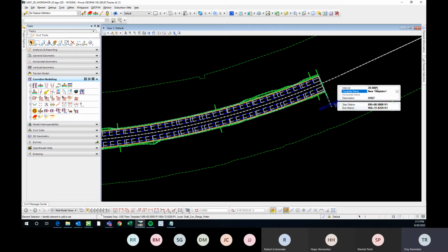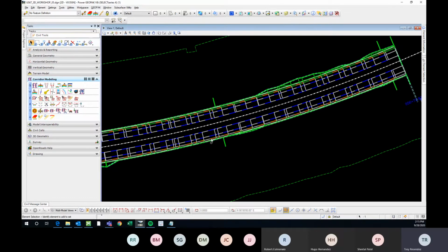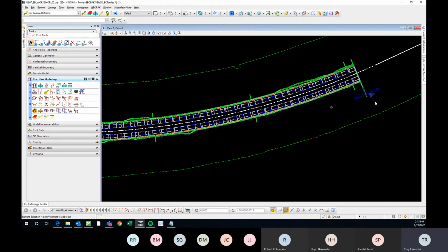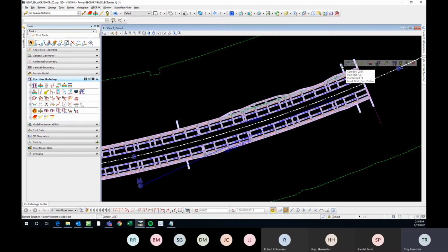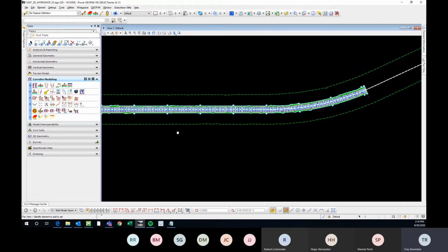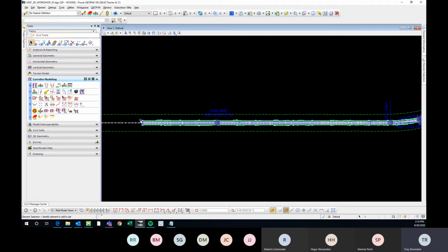Some people may be thinking, well, why don't you change the template drop interval, which you can change here. So let's say if we change it to 10, you can see that it added some cross sections to be solved in there, but I usually just keep this at 20, either 20 or 15, something in that range, and then we'll just change the design stage, because this is how we can control the accuracy of the model. So that's really important to know that.